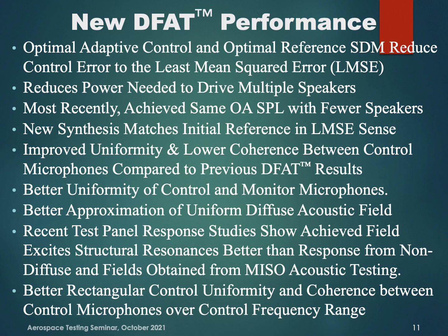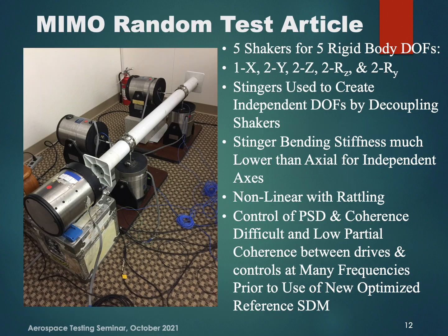It also shows the importance of this, as I discuss in more detail in a paper that I'm also going to be presenting at the Shock and Vibration Symposium later this month. In any case, we achieve better rectangular control, uniformity, and coherence between control microphones over the control frequency range than we previously were able to achieve.